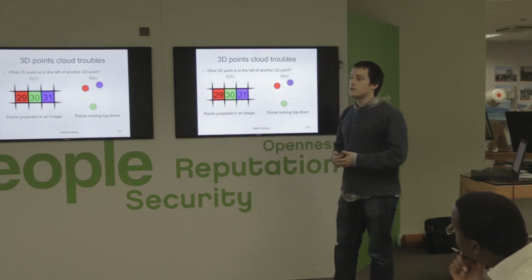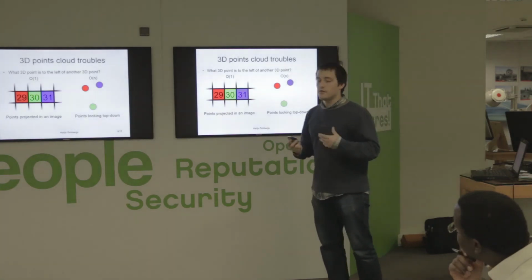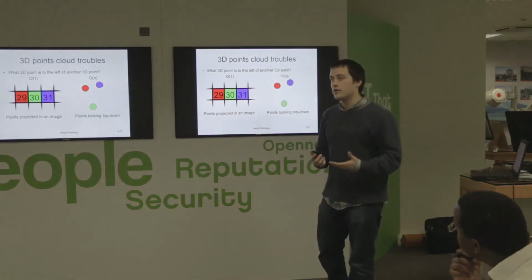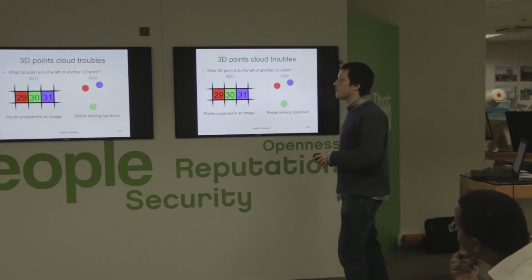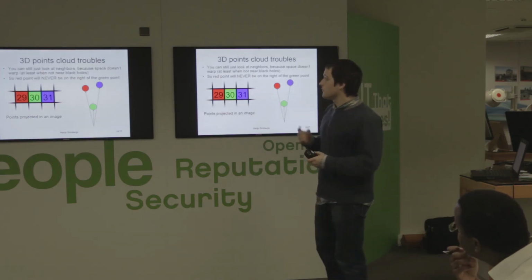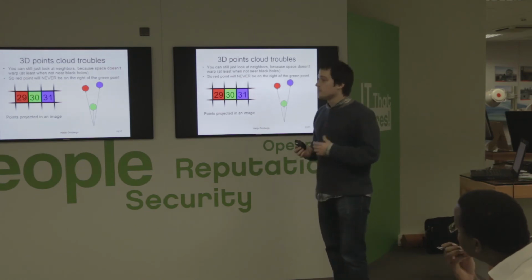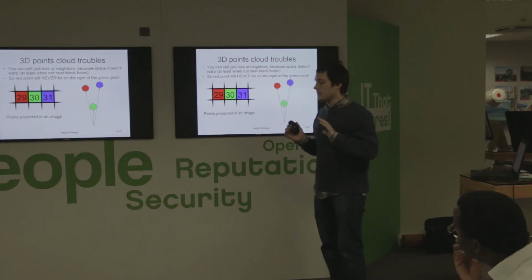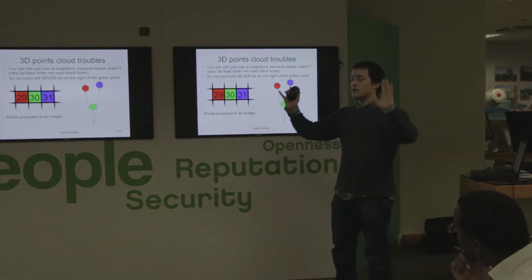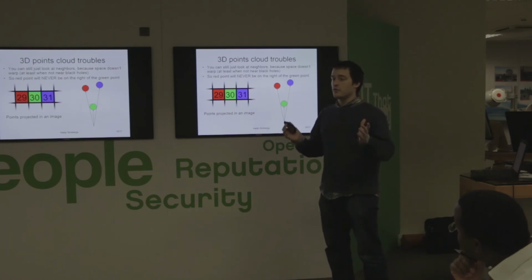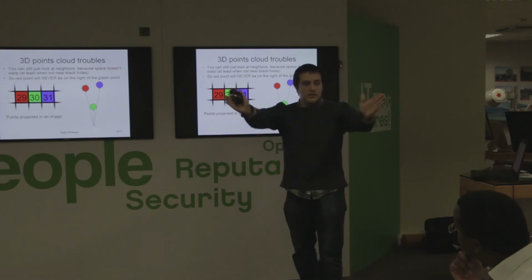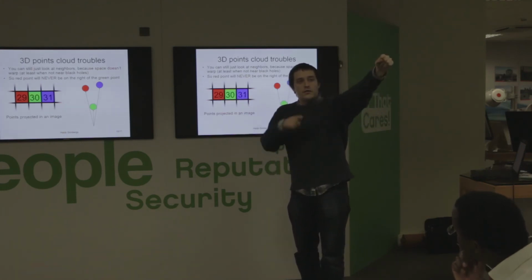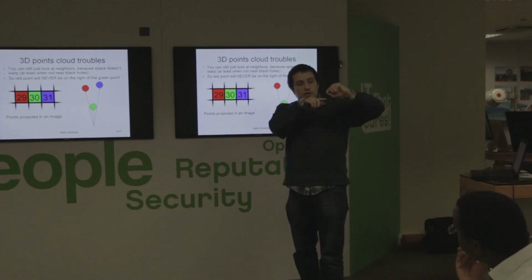And that is the problem why, even on GPUs, parallelization of some point cloud algorithms is very hard, because you basically have to search the whole data that is on the GPU at that time, and that is not that fast. But the bright side is that if you get a point cloud image from, for example, a stereo camera, it looks like a cone. It is like the field of vision, and then it goes out, and the point and the pixel in the image are in a straight line.